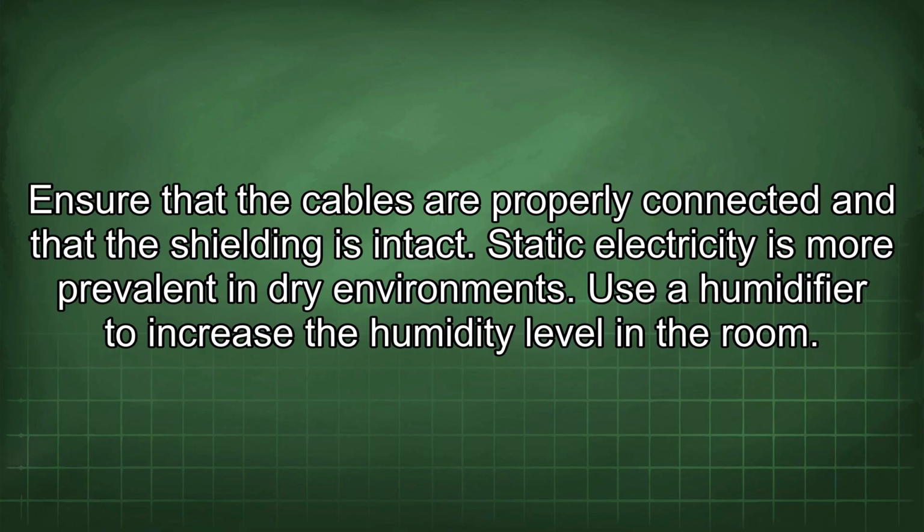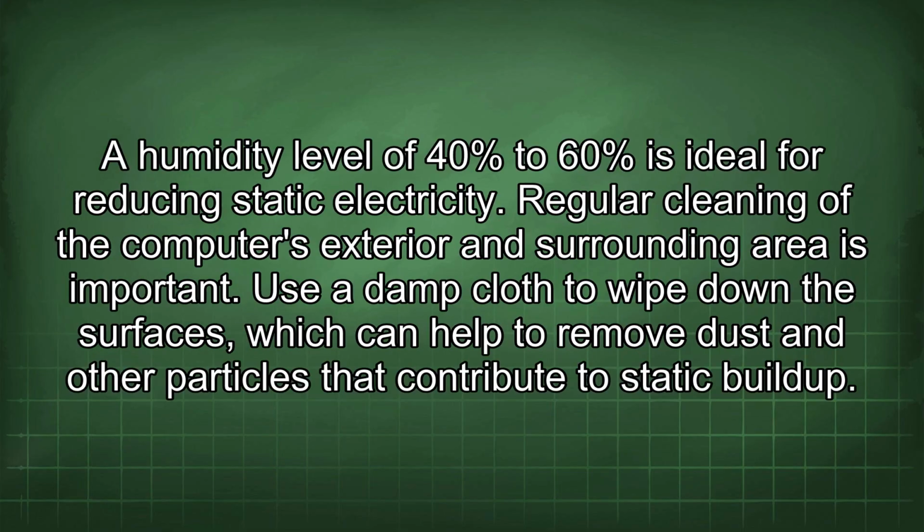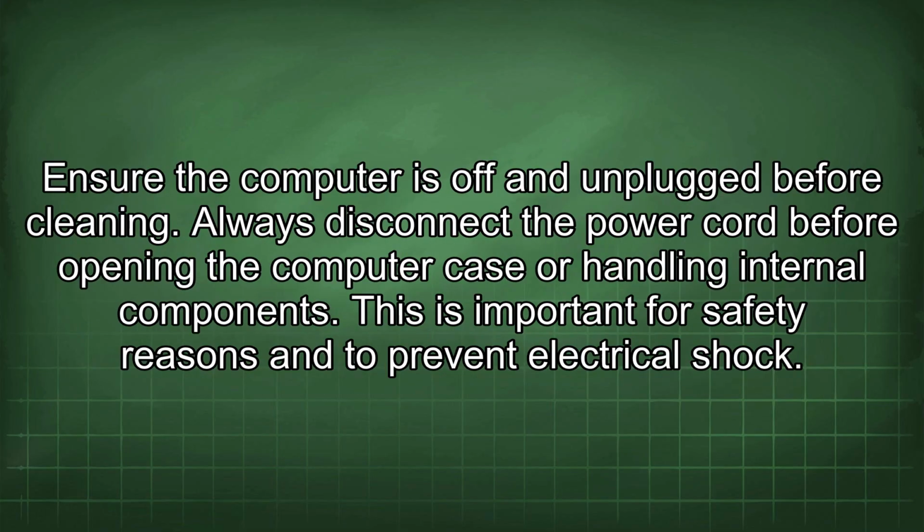Static electricity is more prevalent in dry environments. Use a humidifier to increase the humidity level in the room. A humidity level of 40% to 60% is ideal for reducing static electricity. Regular cleaning of the computer's exterior and surrounding area is important. Use a damp cloth to wipe down the surfaces, which can help to remove dust and other particles that contribute to static buildup. Ensure the computer is off and unplugged before cleaning.